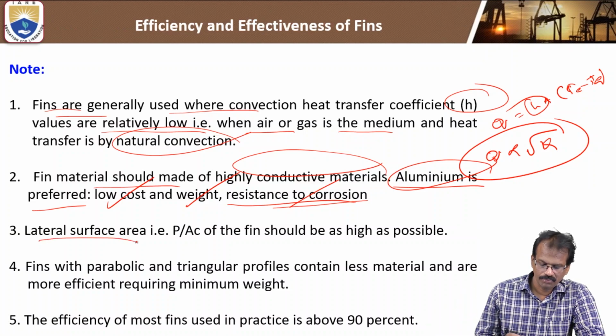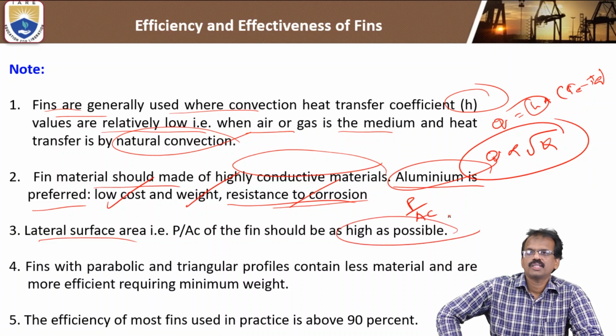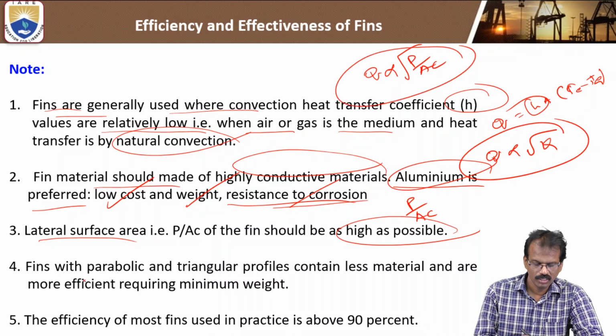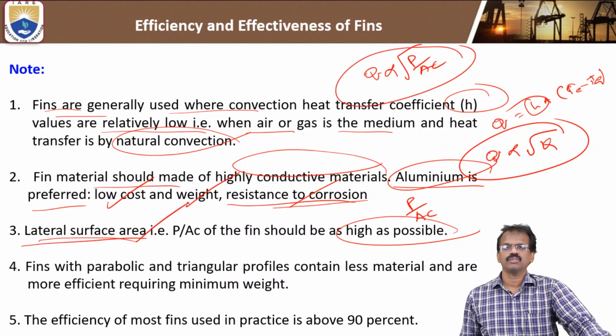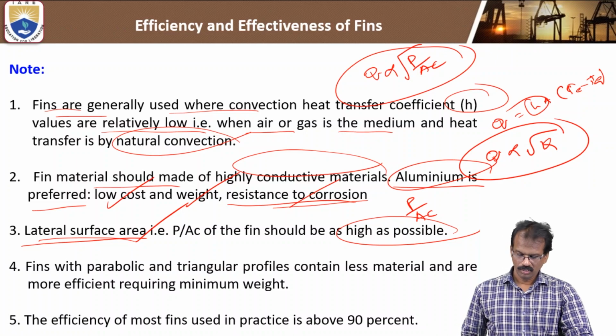Next, the lateral surface area, P by Ac of the fin, should be as high as possible because Q is directly proportional to under root of P by Ac.